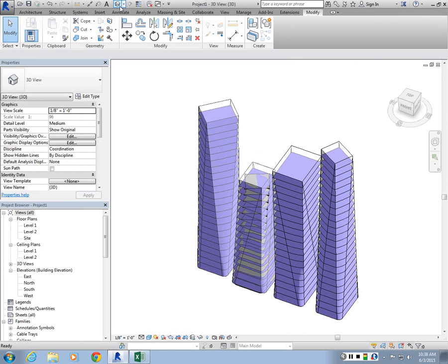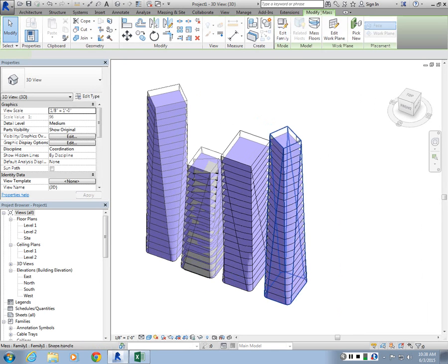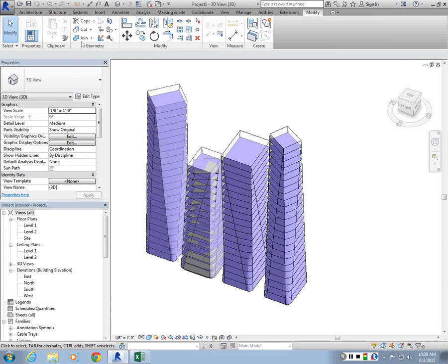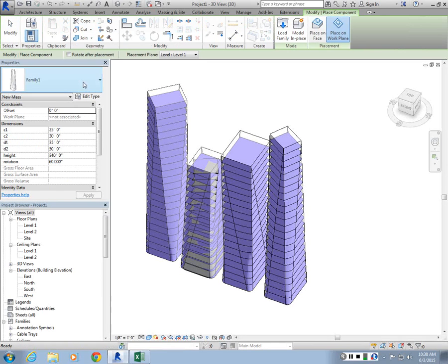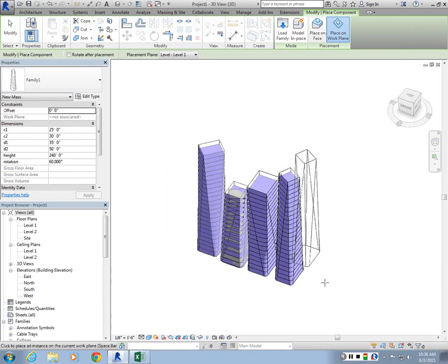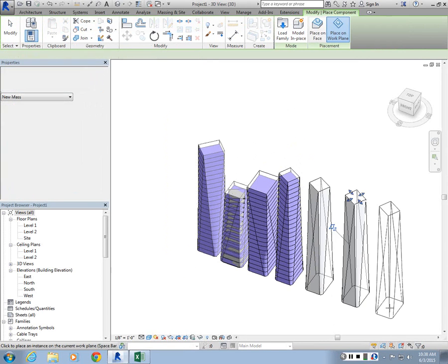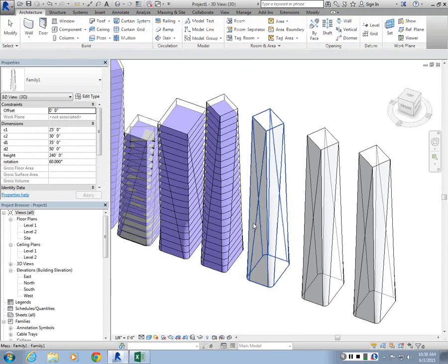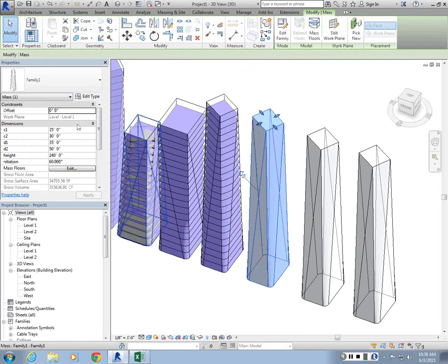So what was your question, Erica? I was saying since the recording is on now, can you do it when you change the individual heights? Sure. You can just bring in another component. This is another family, right? I can bring another instance of these, and any of them can be changed with these parameters because they're instance parameters.